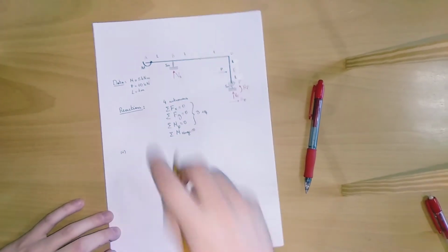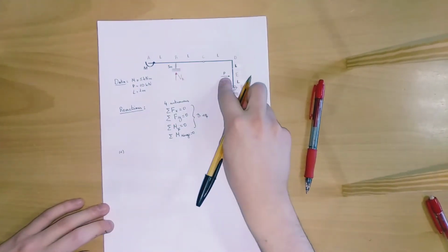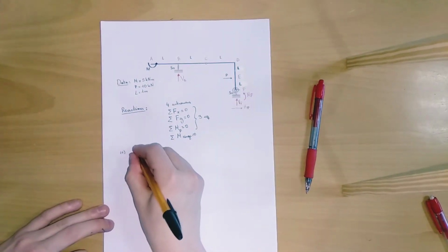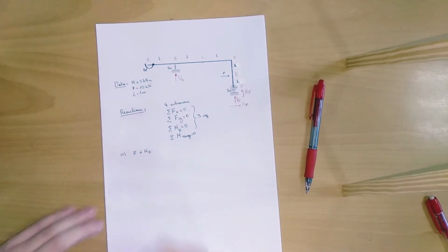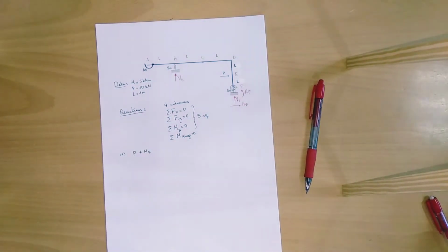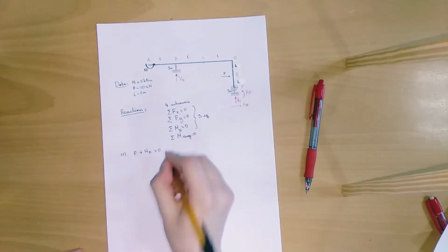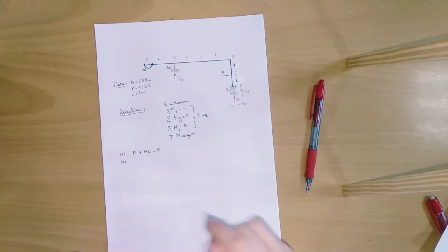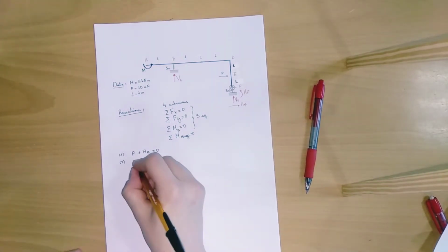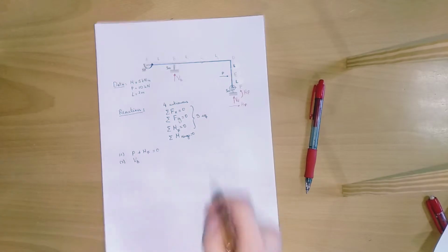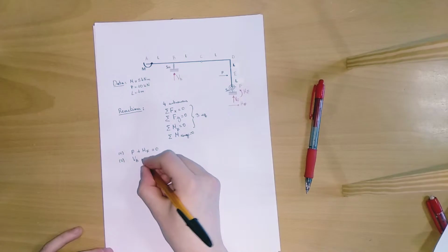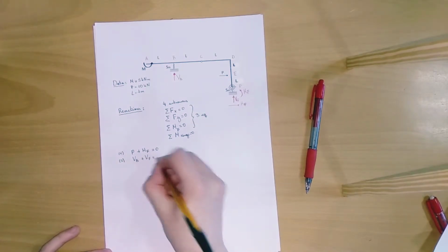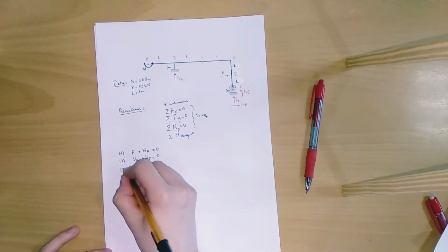We start by the first equation. As horizontal forces, we've got P plus HF, sorry, equals 0. Now, the vertical forces. We got reaction at B, which goes up, so positive. And then we got VF, both of them equal to 0. Now we go to moments.